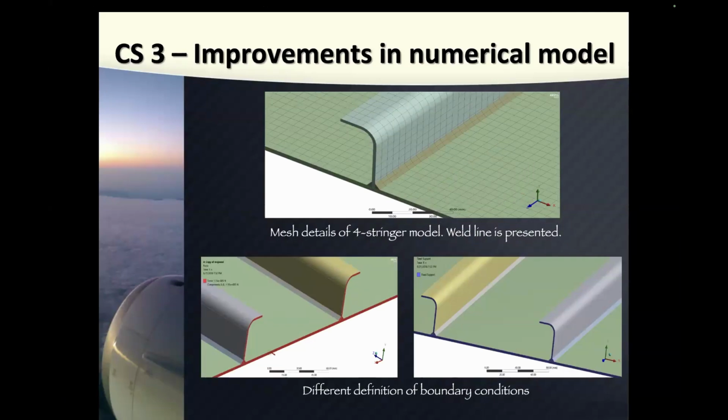So they used some of the methods used in the 80s and 90s of the last century, when you use some approximations, some approximative formulae, okay? So my point is, the experiment was correct, everything was fine, but the values of C and M in the Paris formula were not correct, not well estimated. But the good news is that using these coefficients, I got results which are conservative, which is on the safe side. So no damage will be done on any Airbus aircraft, so don't worry about that. I mean, from the point of view of fatigue design.